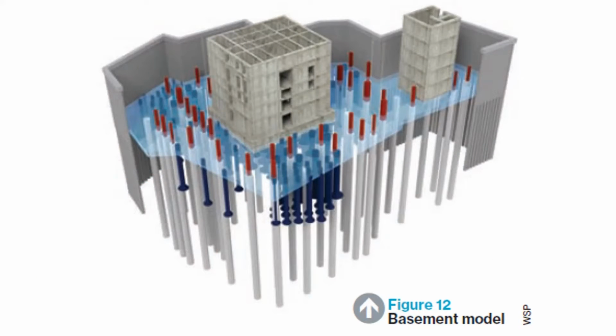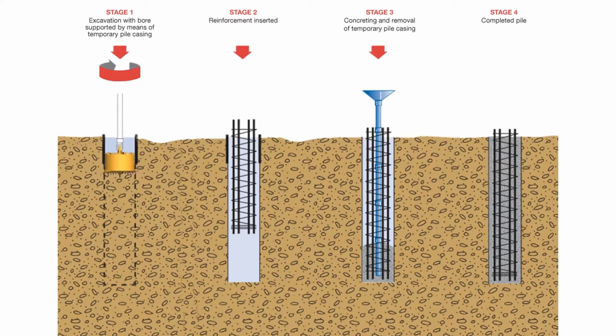And the main bearing piles supporting the raft have 1,800 mm diameter, as well as 1,500 mm diameter, which is similar to secondary piles. This optimized piled raft minimized the amount of excavation and material use. Constructors of the Shard used the rotary bored piling method to make the secant pile wall and foundation piles. This piling method has the advantage of minimal ground disturbance, which means limited risk of damage to adjacent structures.